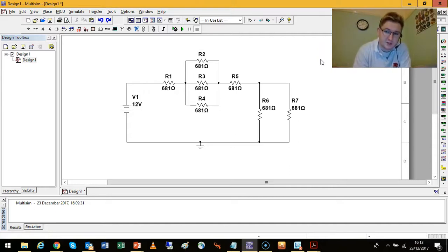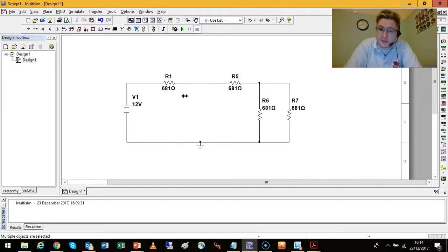So if I'm doing a short circuit, I'm effectively bypassing that by putting a wire loop by it. So effectively I'm lowering the resistance by putting in a short circuit. So by doing a short circuit, I end up with a situation that looks like that. As current follows the least resistive route, the current's going to flow from R1 and it's going to see the short circuit and go straight through into R5. So effectively, it's going to eliminate R2 and R4 from the circuit, so then that parallel combination ceases to exist and we will get a situation that looks like this.